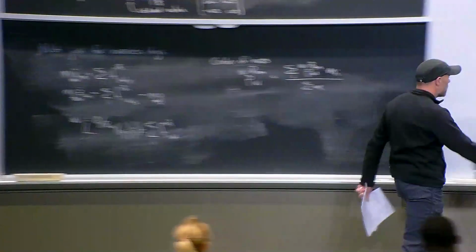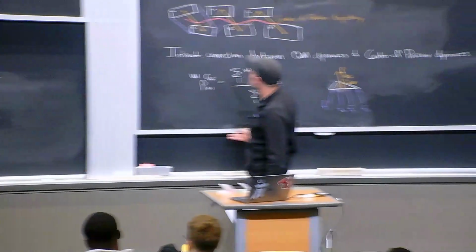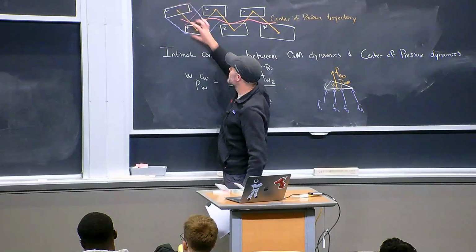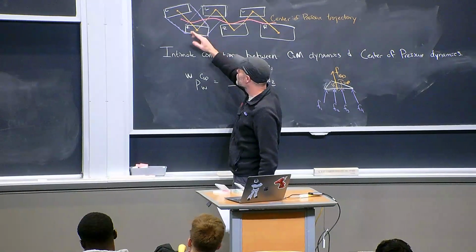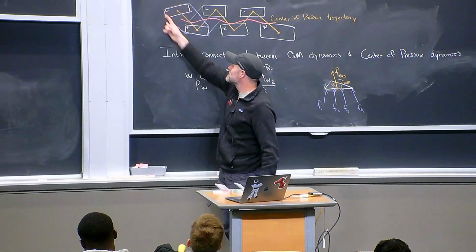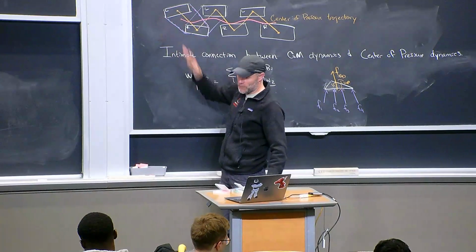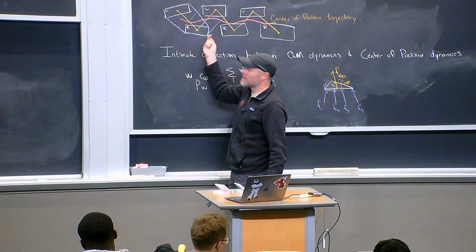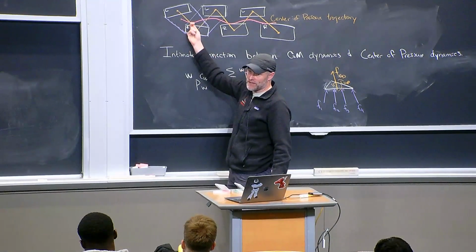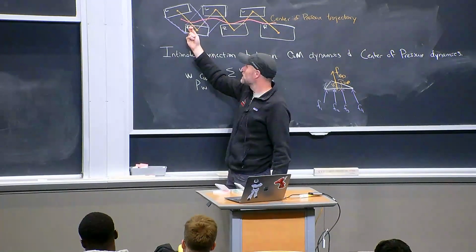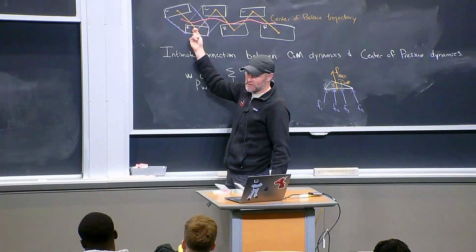Okay, so I'm sorry I said it too quickly. Imagine I have 2 feet on the ground. Then one thing I know for sure is that the center of pressure has to be inside these, because when I'm walking on flat terrain, these are the only places I have external forces. So the average force is absolutely going to be inside the convex hull of this force, and the center of pressure, therefore, has to be inside.